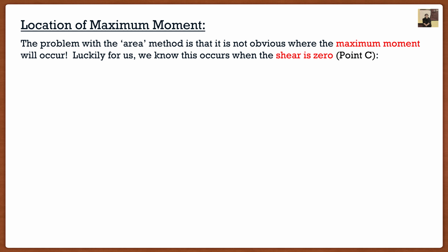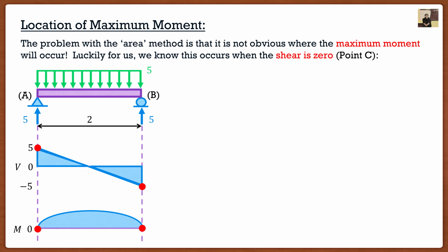And you guys are saying, Clayton, all right, I understand that, but how do we solve for that? Well, again, they're related because one's simply the integral of the other. And we know about derivatives, it's the minimum maximum idea. So what happens is the maximum moment actually occurs when our shear is equal to 0. So again, if we had these and we were to submit this to the professor, chances are we're getting some marks off because we forgot to include two things.